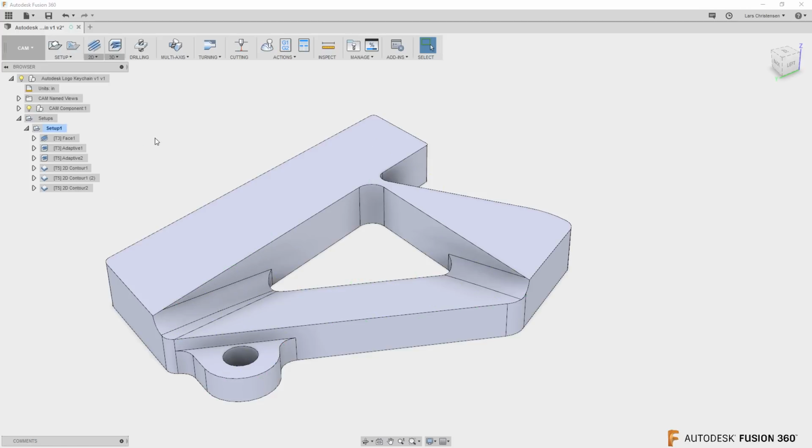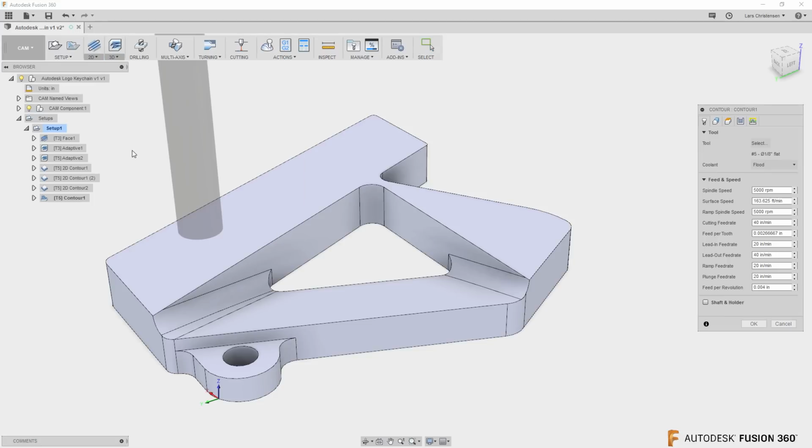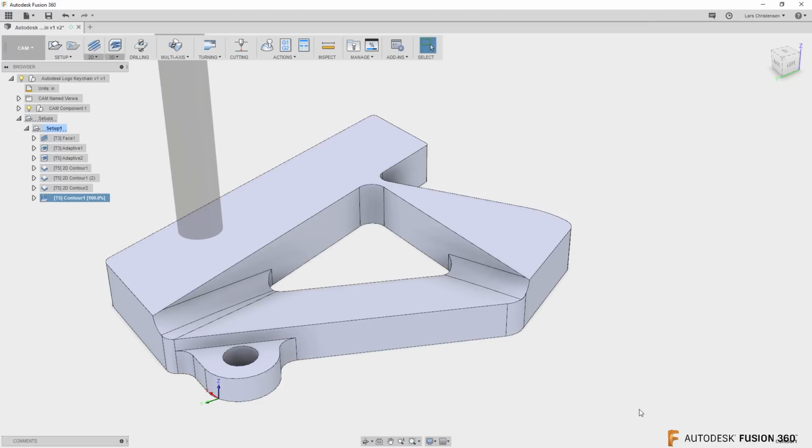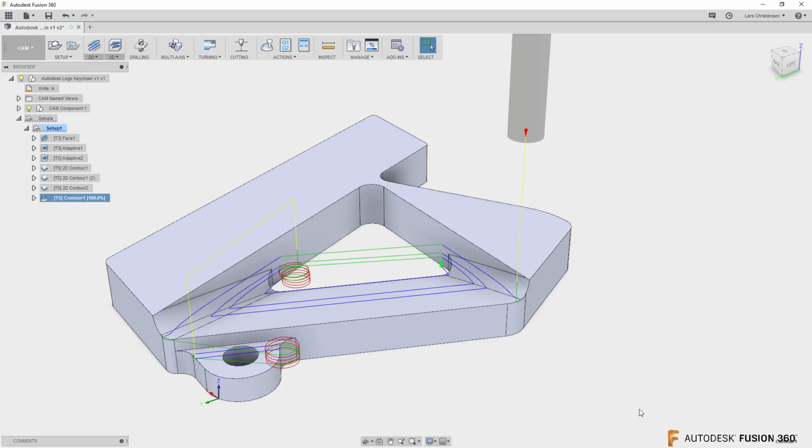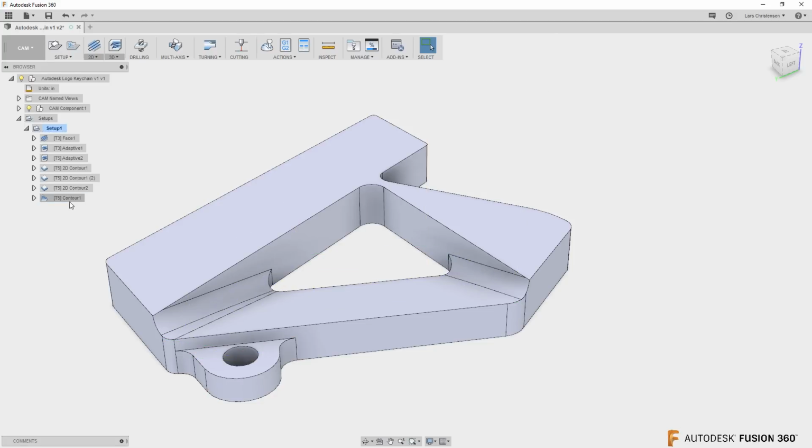The next toolpath that I normally go to would be the contour toolpath. So let me select that. And we still have the ball end mill. Let me just hit OK. Let's see what we get on that. And that doesn't really look like it. It does attack these faces here, but it doesn't seem a good fit for this here. So I'm going to hit OK to that.